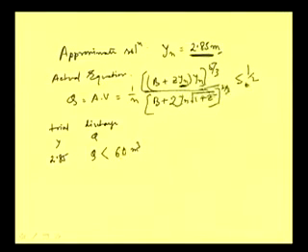So in the next trial, we can increase it to some higher value. Suppose we go to 3.00. Then if you put the value and try, you will find that Q is becoming greater than 60 meter cube per second. And that way, if we carry out trial and error, you will find that for a value of 2.93, we get Q approximately equal to 60 meter cube per second.